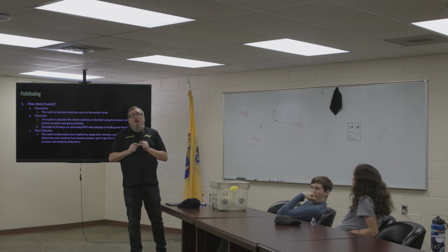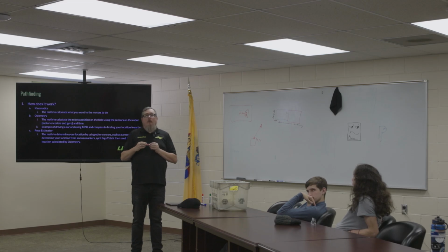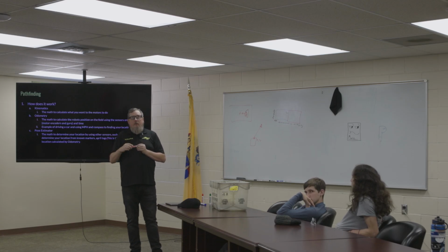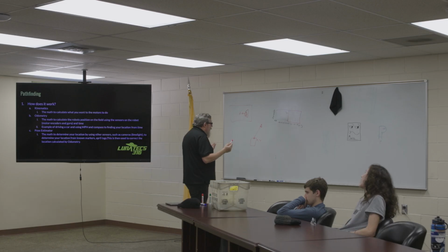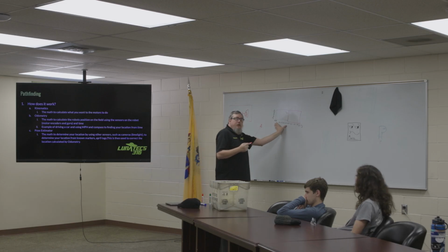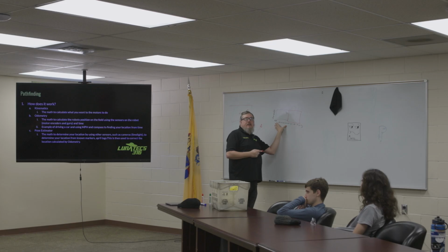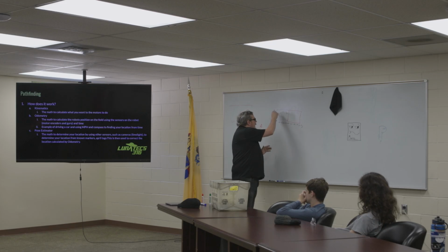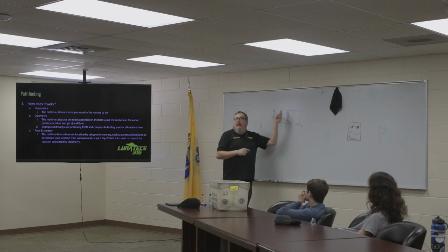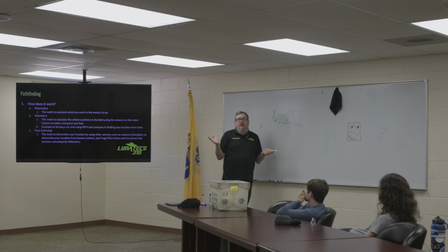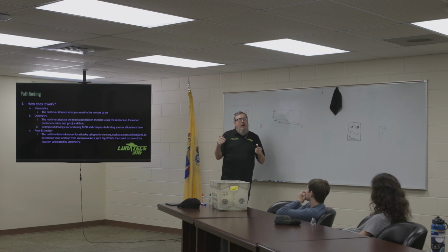The farther away the Limelight is from an April tag, does that have anything to do with how precise it will be? Yes, because the further away, the harder it is to see. But generally speaking, if we're looking at half the field, we're going to get a really good estimate of where we are. If we're over here looking at an April tag over there, that's when it gets a little dicey. But you'll notice that April tags are all over the field. So I just have to see one April tag and I know where I am on the field.